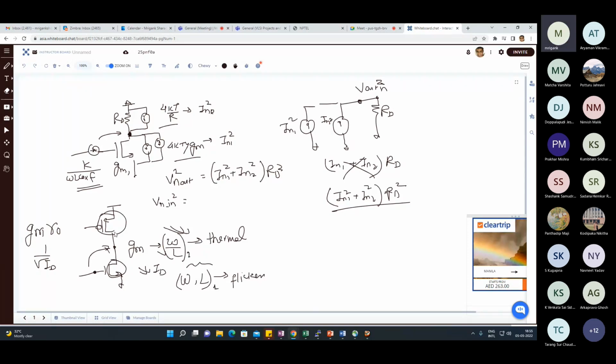For the output device, we have seen that anyway, we have to reduce the gm. Increasing the L, for example, for this device will be reducing the gm. That also reduces the noise contribution of this device. So any question regarding that? This entire discussion on the small signal, also frequency response, and the noise analysis for active load and resistive load has been done in these two lectures.